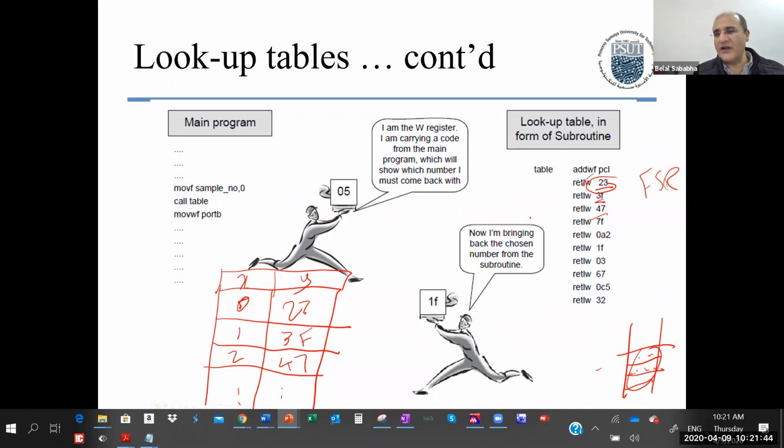So W alone is not going to be enough. So you may have several instructions that store data depending on what you got in several memory locations, but here the memory locations depend, you calculate, you make it indirect addressing mode based on the FSR and INDF registers, okay, when W comes, and then you return normally. You don't need the return with literal in W because you stored everything in a place. So you need to design it differently. This was a very simple one for one value.